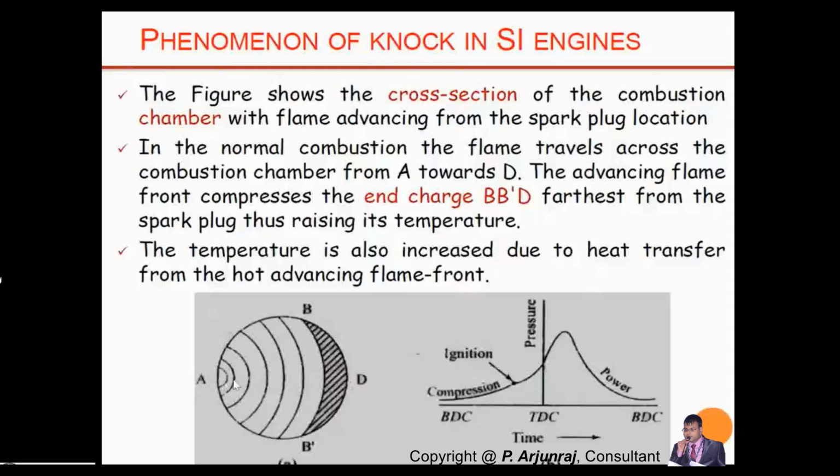You see here, when the flame is advancing and reaching the longest distance, approaching nearer to point D, the flame compresses the end charge.